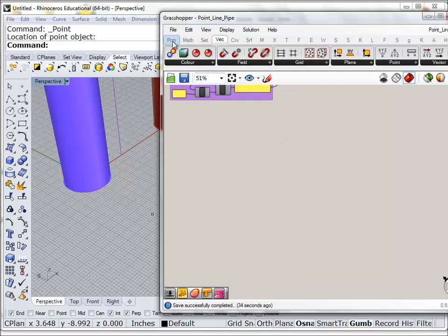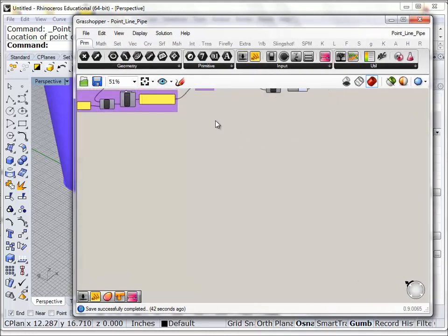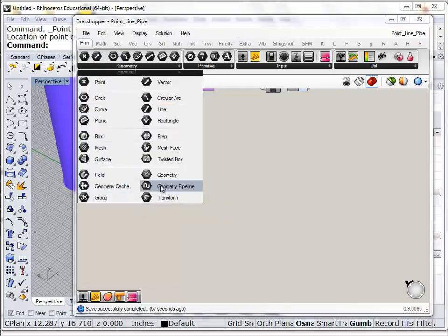If you remember, under Param, we said that this whole group of components would allow us to not only use input geometry, but also reference geometry or transfer geometry. So now we're going to look at how to reference geometry from Rhino. Under the Geometry tab here, you can see that we have a lot of different geometry containers. In this case let's use the geometry point container, because I want to reference that point back into Grasshopper.